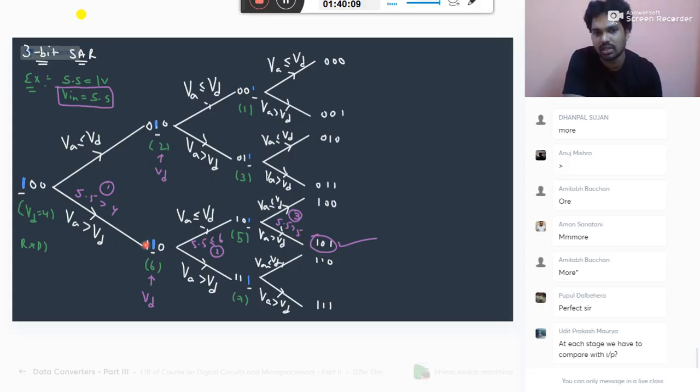Then again it will do the same repetitive process. Okay, input is here less than 6. Then reset this bit. Set the next bit. Same story. Here also it will check. Input 5.5 is greater than 5. So then retain that as it is. Whatever you get in 3 steps, that is the final answer. You check for any random input, it is the same story.